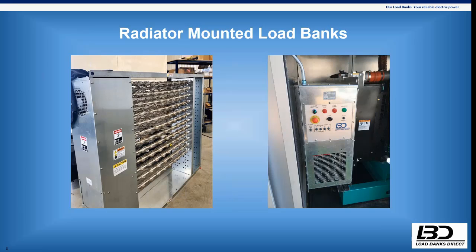It's not always the best solution, because if you need that higher capacity, then you need to go into a stationary application. But in a duct-mounted application at 30, 40, 50%, where you want to supplement or keep a minimum load, or meet the NFPA 110 requirements of testing that generator under load, or getting the engine up to operating temperature to minimize the adverse effects of wet stacking and unburned fuel deposits building up within the engine, this is a great solution.